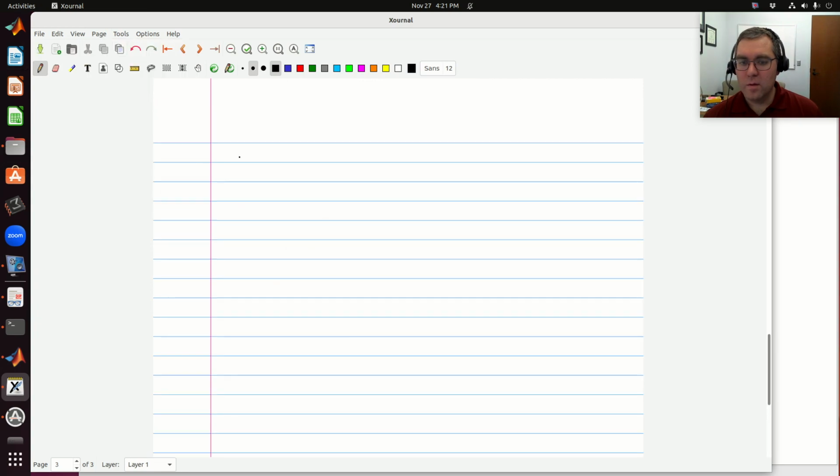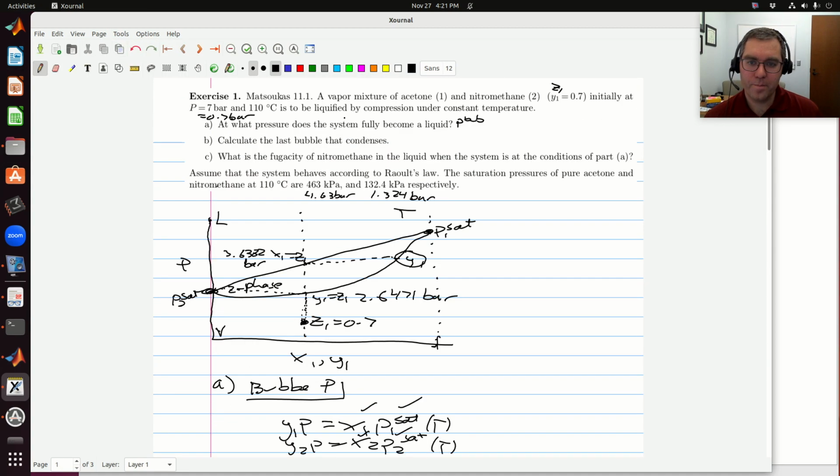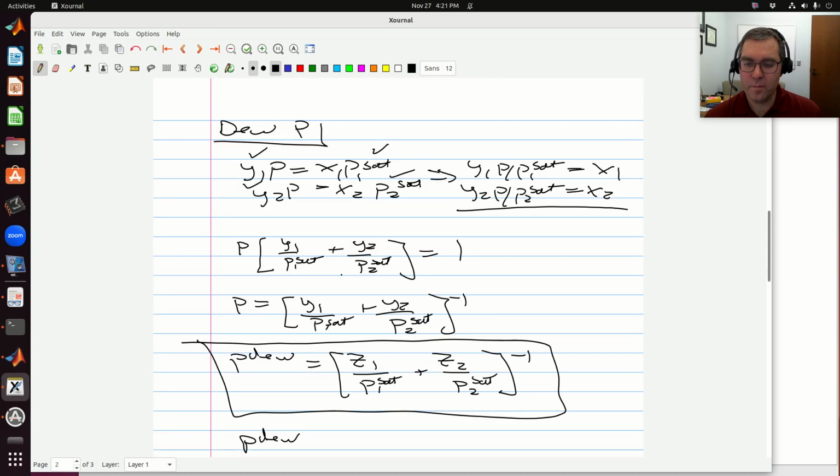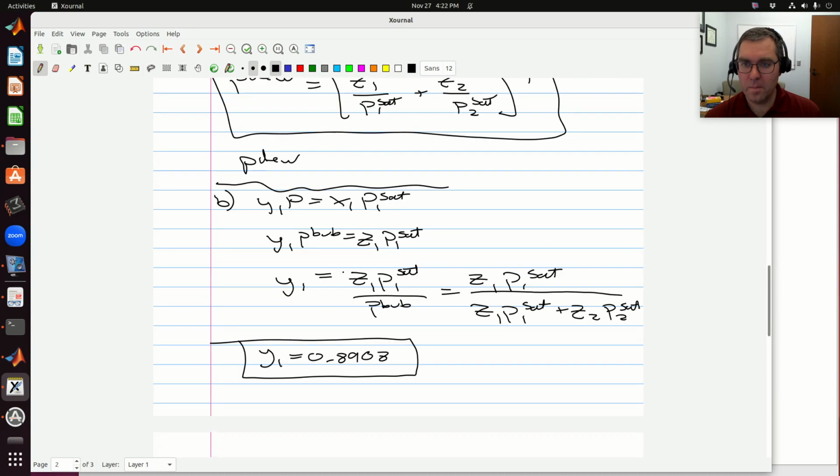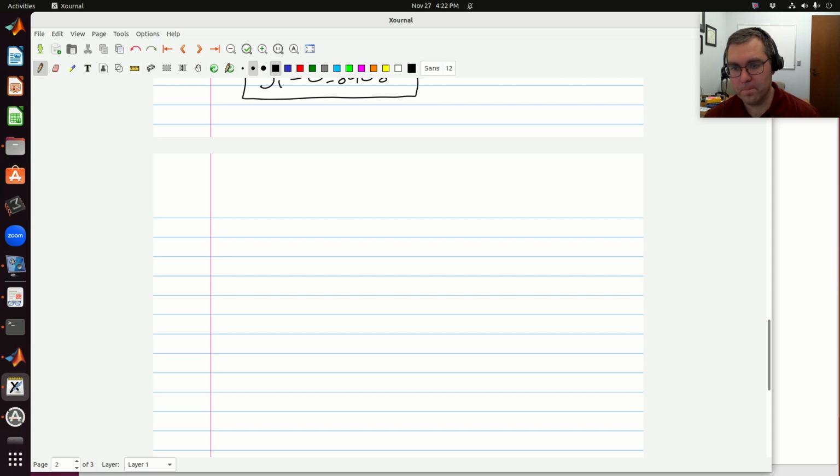That's good. Then the last part asks: what is the fugacity of nitromethane, that's component 2, in the liquid when the system is at the conditions of part A. So for part C, at my bubble point, we're asked to calculate the fugacity of component 2 in the liquid phase.